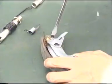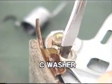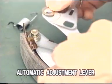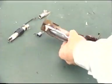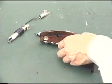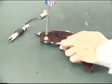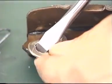Remove the automatic adjustment lever by pulling up the C washer with a screwdriver. Then remove the parking brake lever from the rear brake shoe by pulling up the C washer.